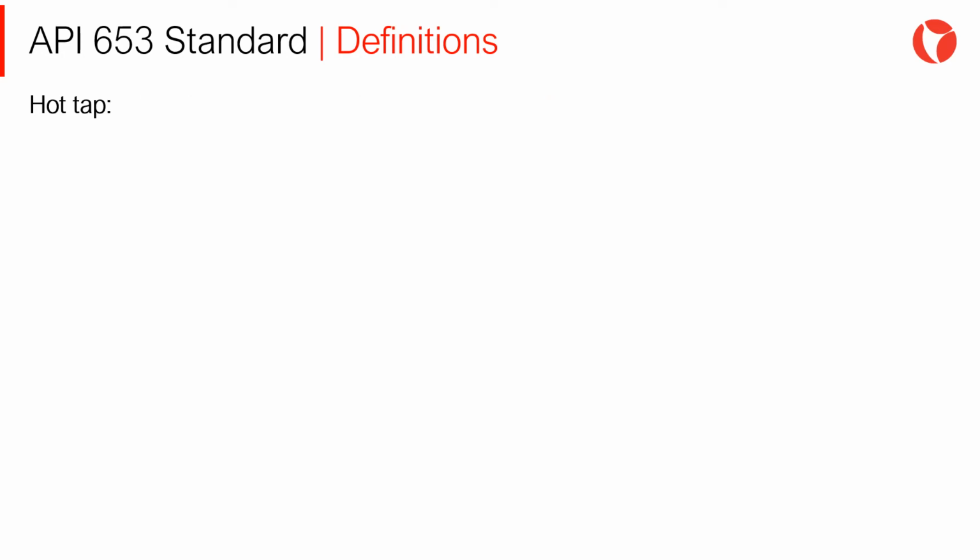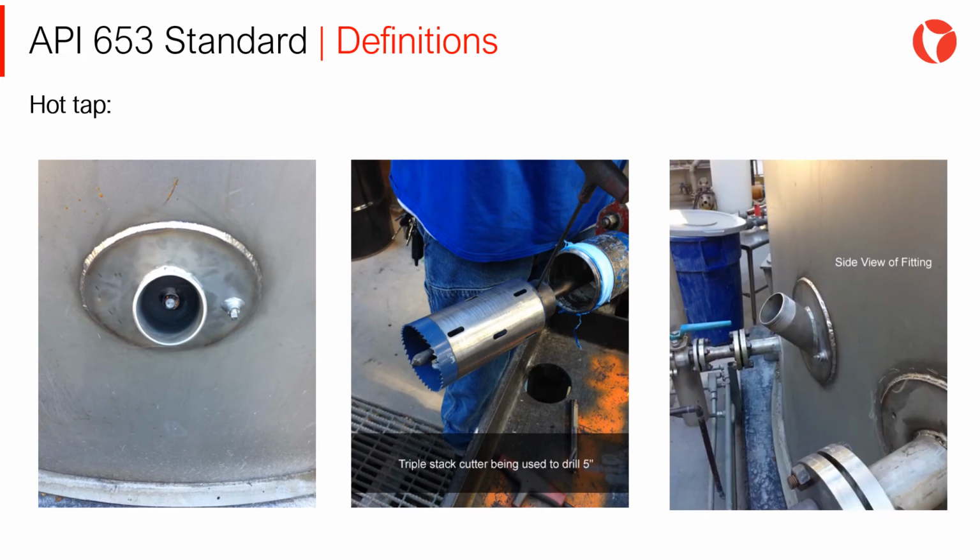Let's now review a hot tap intervention in a storage tank. First, the neck of the penetration and reinforcement need to be welded to the tank shell.